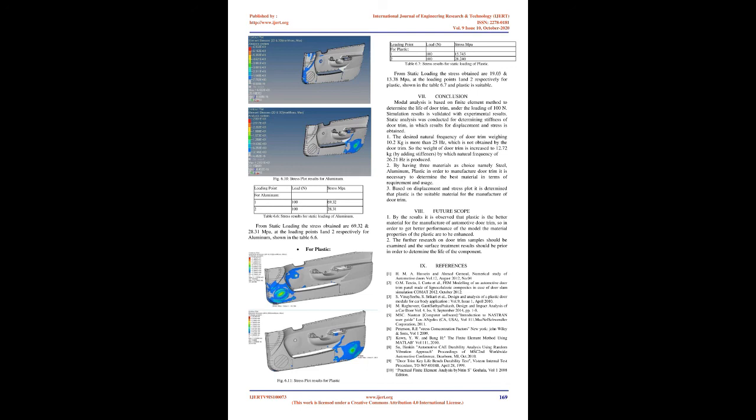7. Conclusion. Modal analysis is based on the finite element method to determine the life of the door trim under the loading of 100 N. Simulation results are validated with experimental results. Static analysis was conducted for determining the stiffness of the door trim, in which results for displacement and stress are obtained. 1. The desired natural frequency of the door trim weighing 10.2 kg is more than 25 Hz, which is not obtained by the door trim. So the weight of the door trim is increased to 12.72 kg by adding stiffeners, by which a natural frequency of 26.21 Hz is produced.